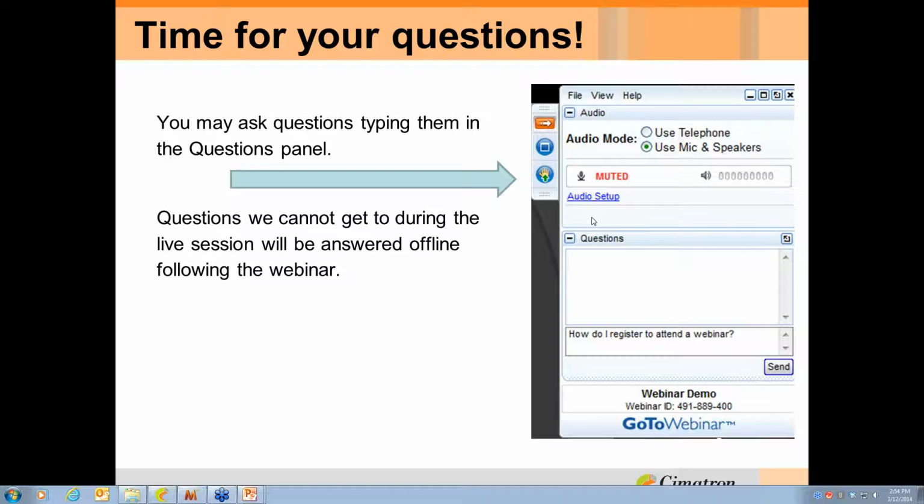Cimatron is actually working on and has developed some other nice tools for dealing with these types of models, because they're not solids. STL files are really point cloud data. We can do some things with them, machine them. In our next version this spring, we're actually doing cuts on them, and a lot of the things that you would think would be only a solid on STL. So again, conformal cooling, it's going to be different for every shape, but yes, Cimatron's very capable of helping design those types of channels.